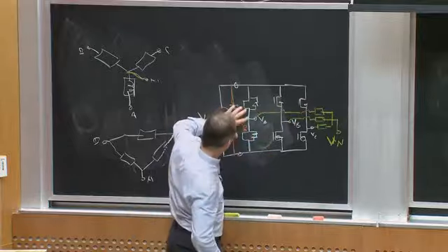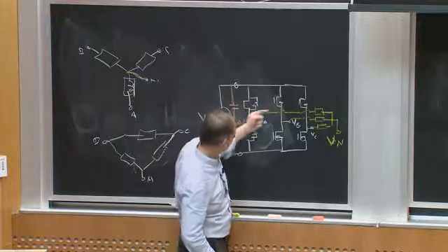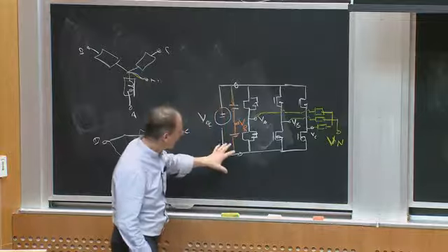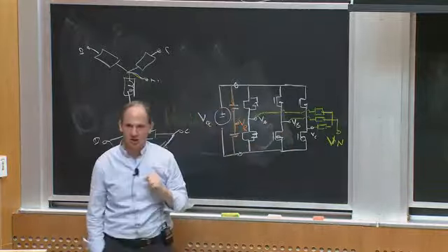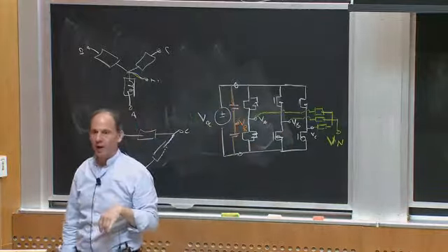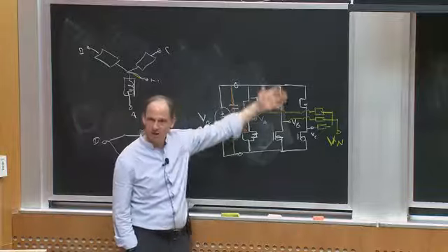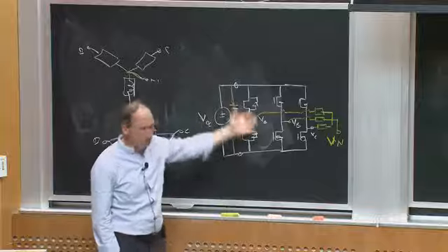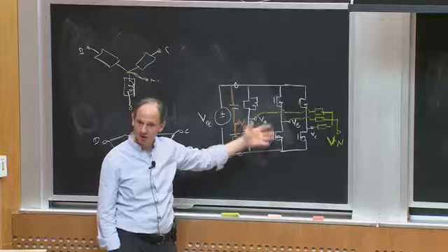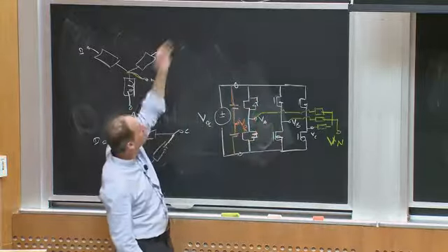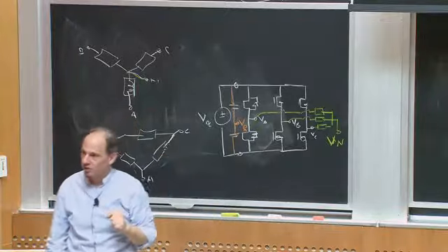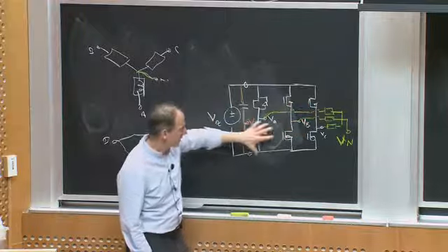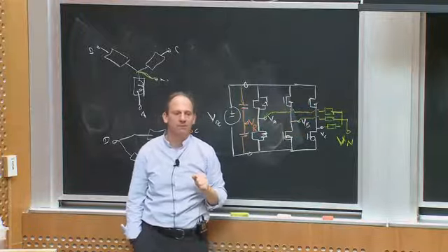Because this circuit, like this phase leg, whatever current goes out, it returns through one of the other phase legs, I get an advantage in terms of the utilization of the devices. So I will either require less semiconductor area to get a certain conduction loss in this structure, or I will have lower conduction loss for the same semiconductor area as compared to the top solution. So this solution in most 3-phase applications is vastly preferred.